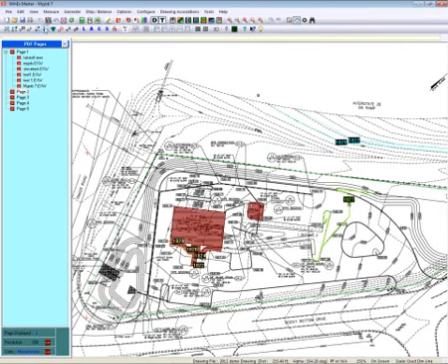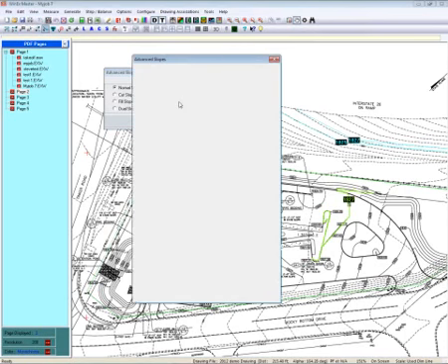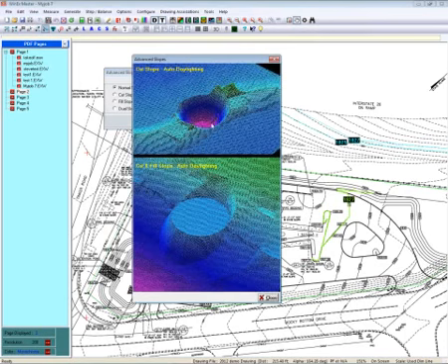We can do retaining walls. We can do some very advanced slopes, where you need to sink a pad to a certain level. You know the angle you need to come out at, but you don't know where it's going to daylight. The software will automatically daylight to the proposed topographics based on all that cell information you put in, because we go out and we grab that and all those thousands of cells. So we'll auto daylight that.